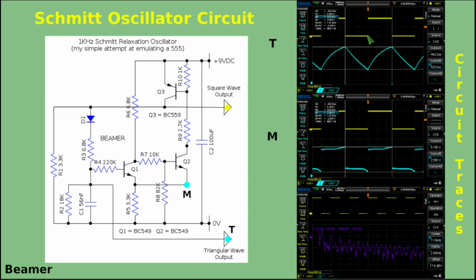One of them is of a low impedance source, which is Q3, turning on. The falling edge here, negative going edge, is limited by the fact that it is a pull down resistor, which is R1, and that can impose limitations. If you have a capacitance on here, the rise time would still look nice and sharp, but the fall time would have a slope on it, and as the capacitance increases, so that slope would increase.